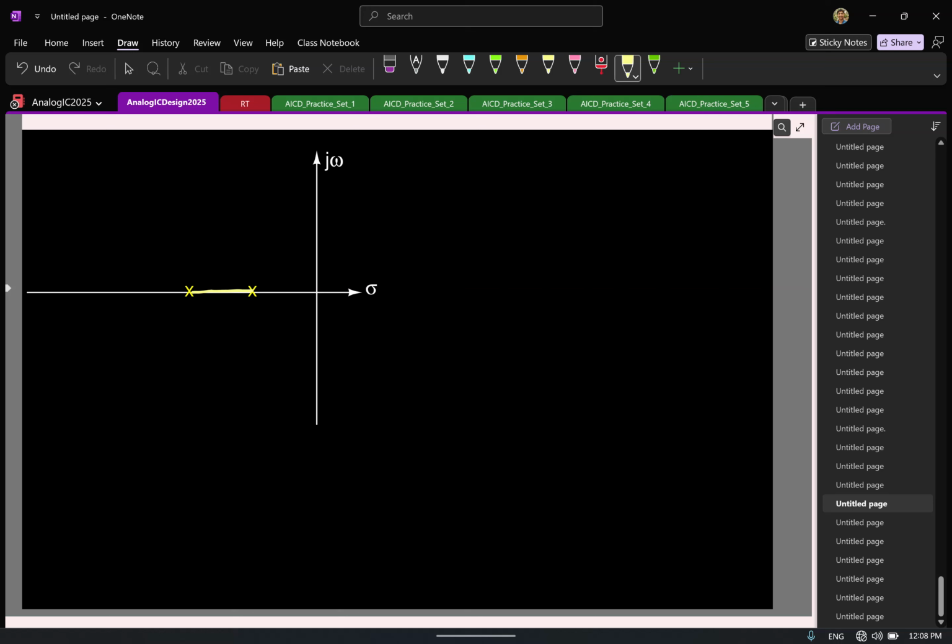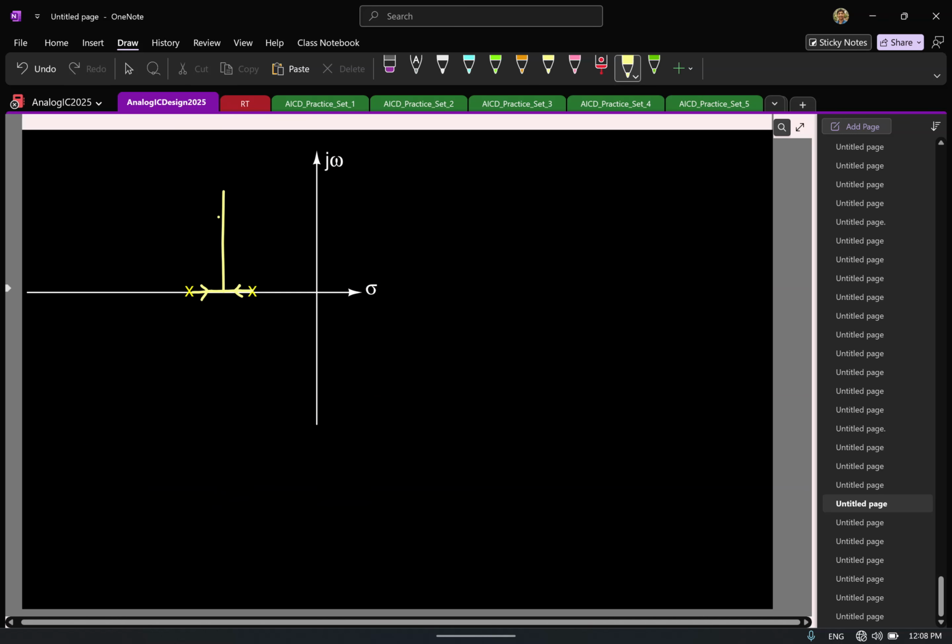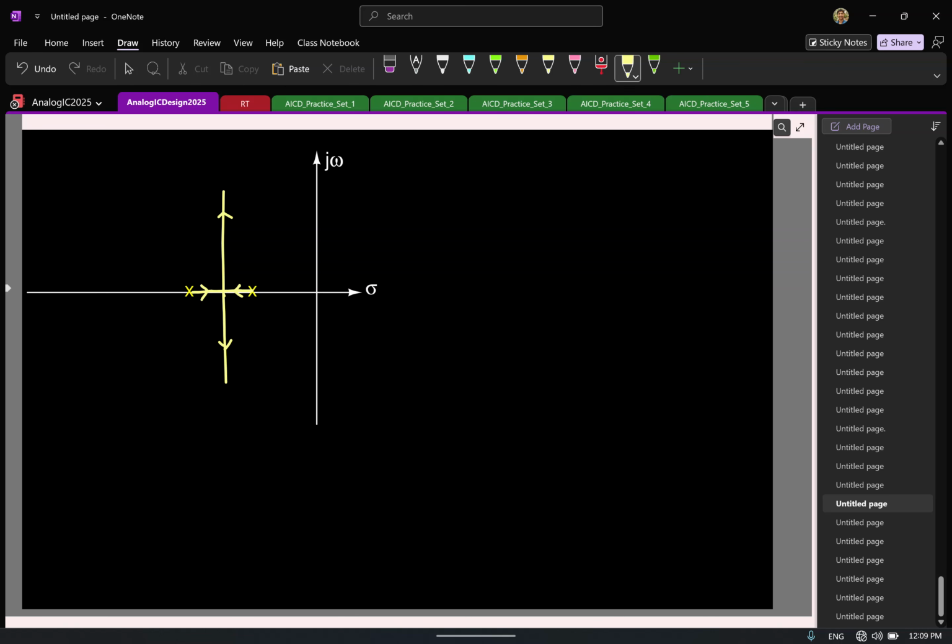Correct. So which means as you keep increasing the DC gain, one pole starts to move this way, the other pole starts to move this way. Now, of course, they have to terminate at infinity. If it cannot go on the real axis, where can it go? In the S plane. Again, I have the whole 360 degrees of the S plane. So the logical thing to do is one takes the top half, the other takes the bottom half.